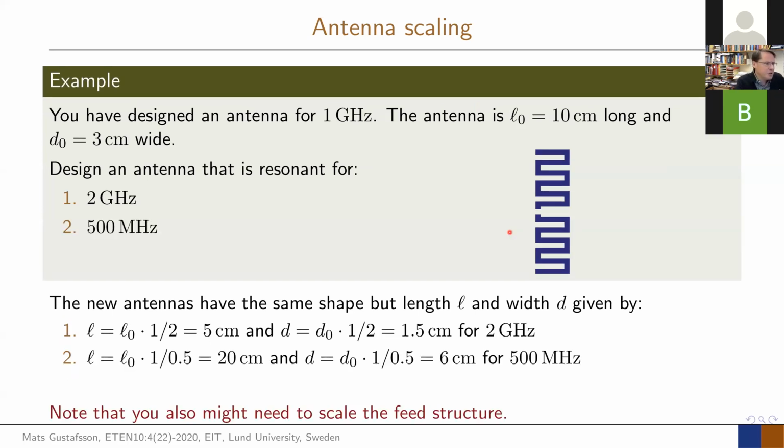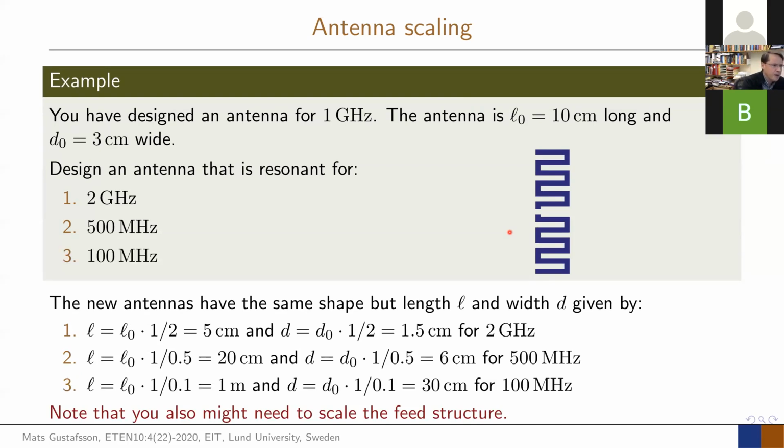Okay, and if we of course do it in the opposite way, so 500 megahertz, it should be double the size instead. And if you go even further down, a factor of 10, then it's 10 times the size, and you just scale it on. So if you have one of those designs, you can do every design. And it's valid for basically all antennas. It doesn't have to be a dipole. It works as well in a meander line structure or patch antenna and so on. It works for basically all of them. Just scale all dimensions.